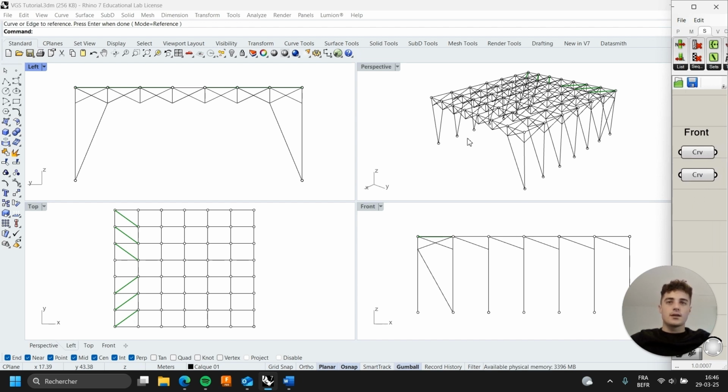And next, we need to brace the XY plane. So to do this, we connect each truss to diagonals, as we can see in the front view there. And we see that in the left cell, this one, we added an additional diagonal to improve the bracing. And the same applies to the supports bar, where we also added a diagonal there.